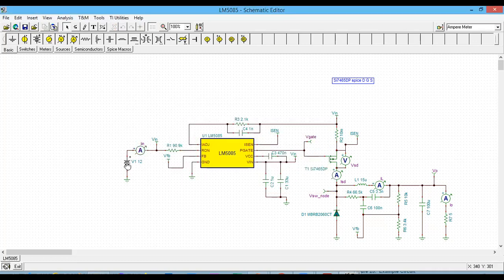So when you simulate, you know your input voltage and you know your input current, so you can calculate the input power. And from here, you know your output current and output voltage, so you can determine the output power. So the efficiency is simply P out divided by P in. So all the losses happening here and everything will be counted internally. But if you know the output power and input power, you can determine the efficiency of the system, right?